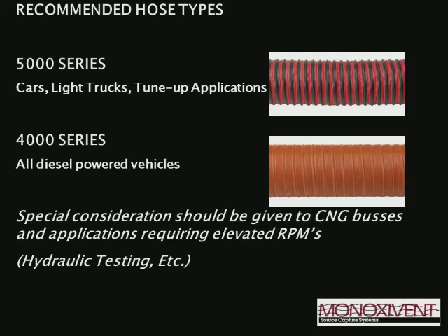Special consideration should be given to compressed natural gas buses or anything that runs compressed natural gas. It's not only buses that use it. I think buses is where it started. We are seeing more over-the-road semis and vehicles like that using compressed natural gas. Compressed natural gas burns hotter than diesel, so if there are vehicles burning that fuel, we need to know that so we can apply the appropriate hose.